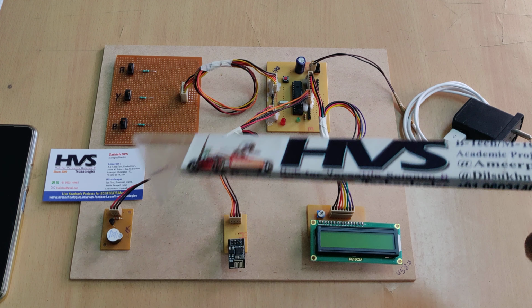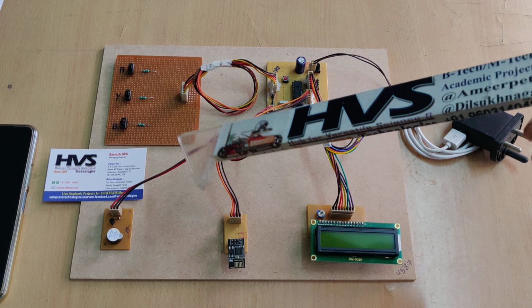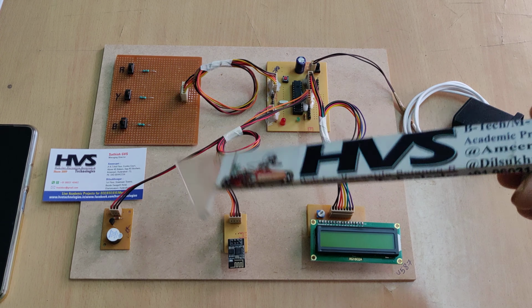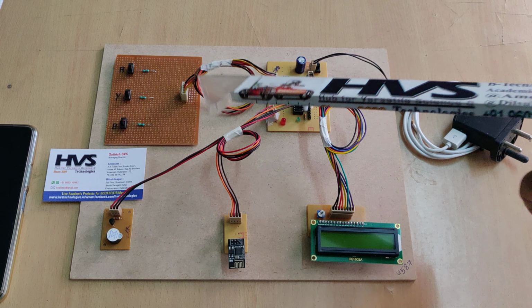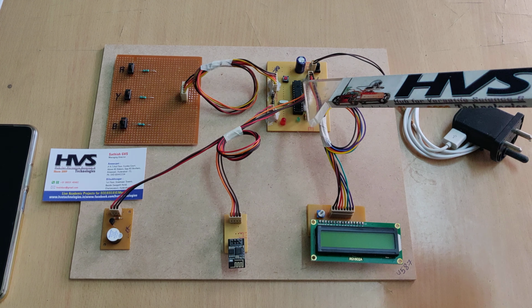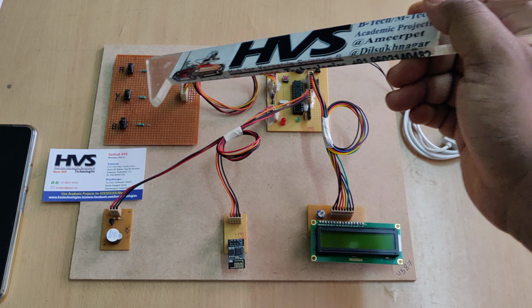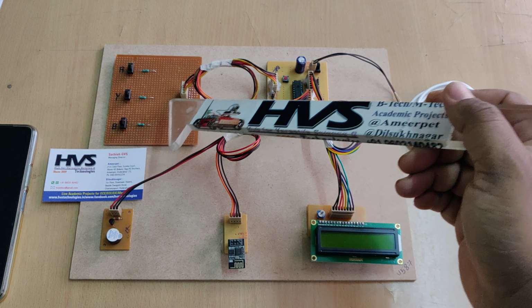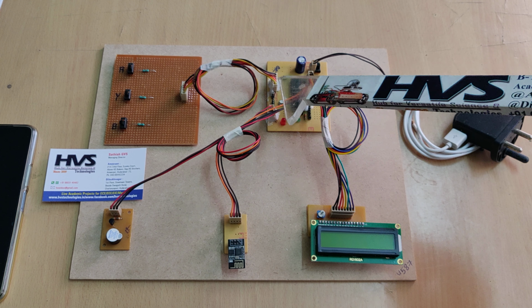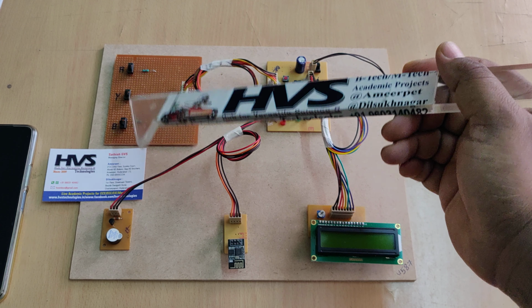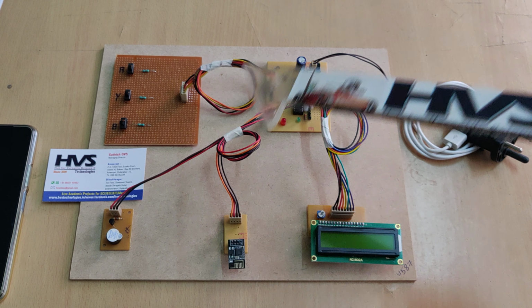In real time we are going to use a potential transformer in order to check the power supply availability in the particular phase. If any line to neutral fault occurred, then automatically the power supply will be isolated and that will be identified by our PIC 16F73 microcontroller, and those sensing connection pins are interfaced to the A0, A1, A2 pins.